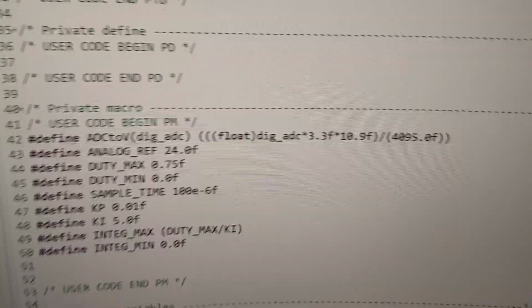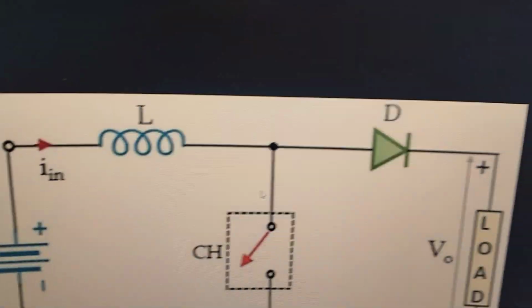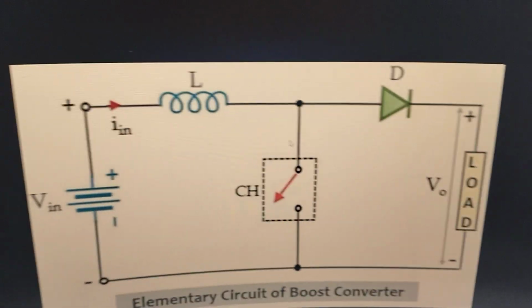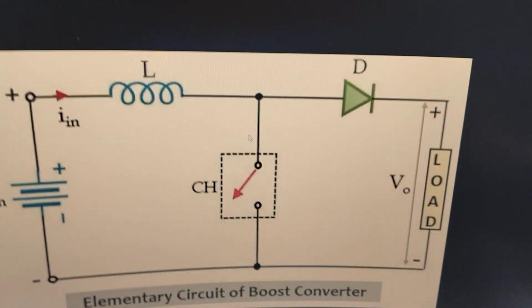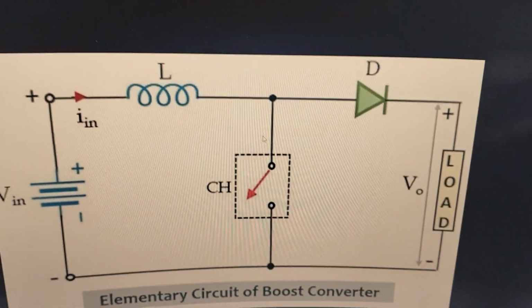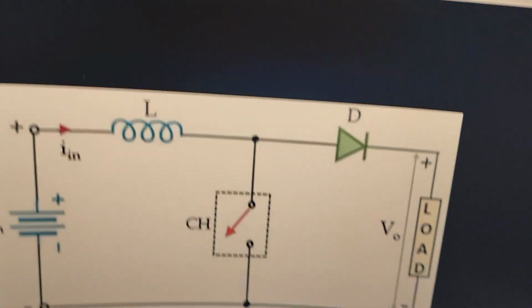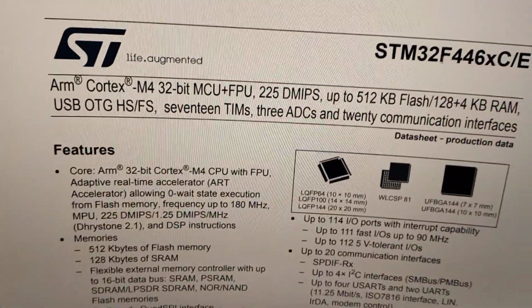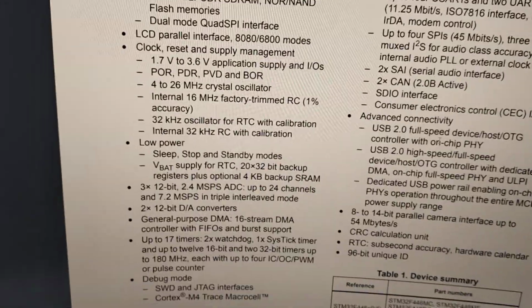This is basically because our output voltage across the load will be much higher. Let's say today I'm going to be doing, the input is going to be 12 volts standard, and the output we are going to be trying 2-3 voltages, maybe 2 voltages. But definitely high voltages, something like about 20 volts. So you can't directly feed that to your ADC, right? ADCs generally have a very narrow voltage level, and since this is a 3.3 volt microcontroller, same as the MSP, you can give maximum 3.3.